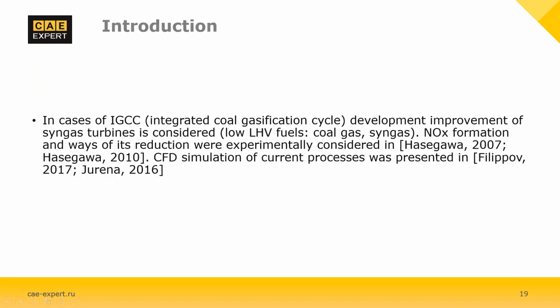A hybrid coal gasification process for the purpose of hydrogen production, which was developed in Japan, and the integrated coal gasification fuel cell combined cycle pilot plant, which consists of gasifier, fuel cell generating unit and gas turbines, in test operation from 2002 from Electric Power Development Company in Japan.